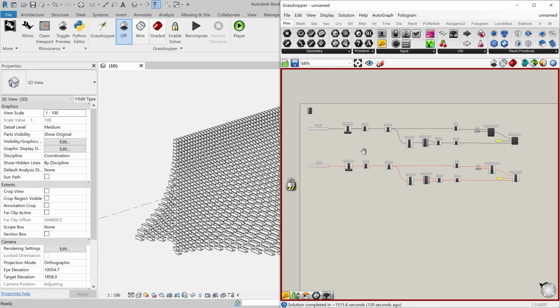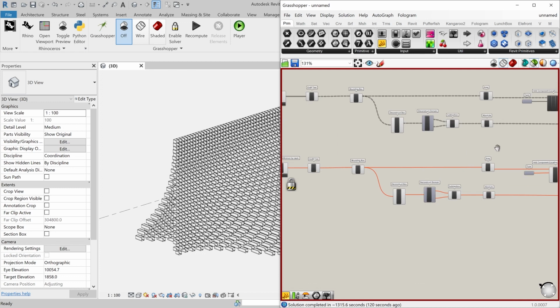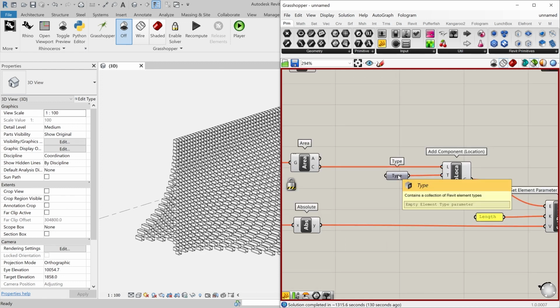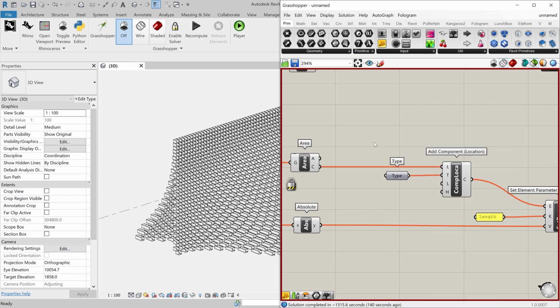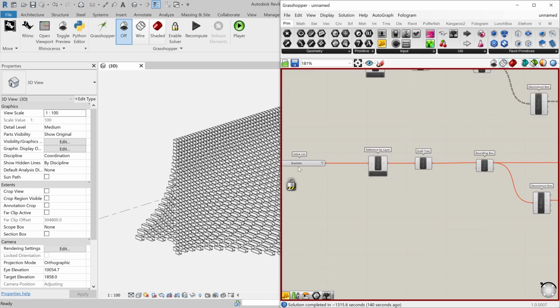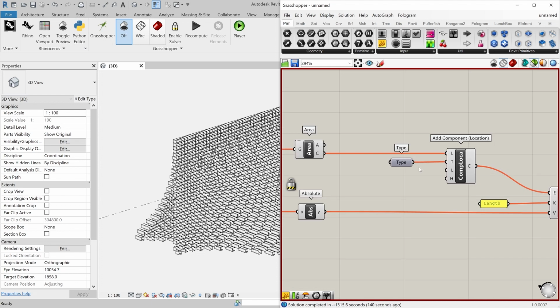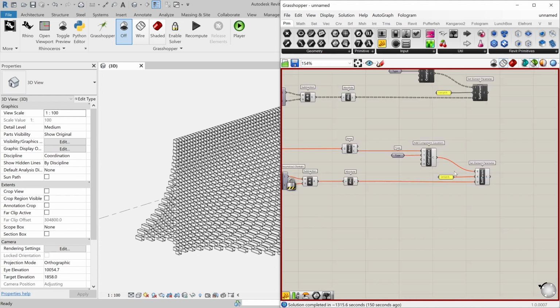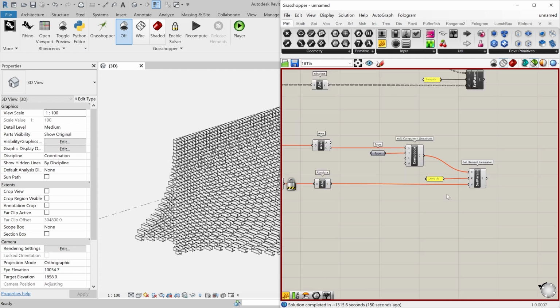One thing I forgot is we've changed, so we're now referencing the brackets, but we also need to change the family that we're placing. I almost forgot that. So if we go back to this, we want to choose the X bracket, because that's the bracket that's in between each box. So we can copy this same snippet down, but what we're inputting is the brackets, and what we're outputting is the L shape. It still has the same length parameter. I made the same parameter for that family as well.